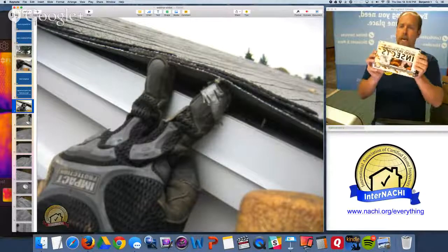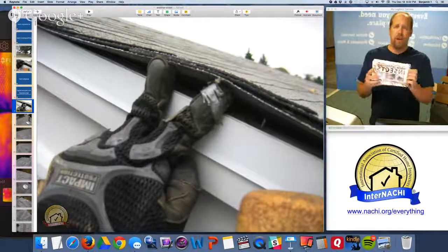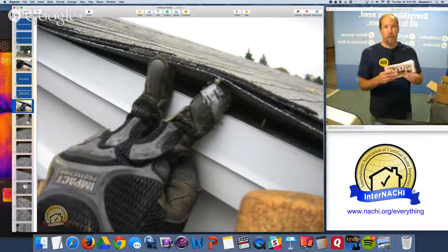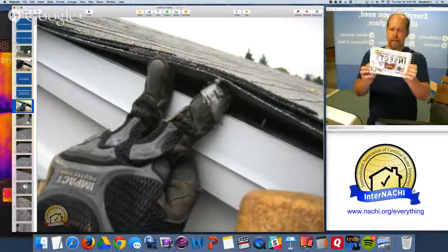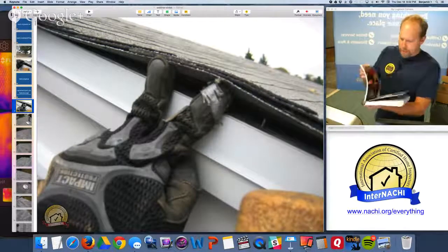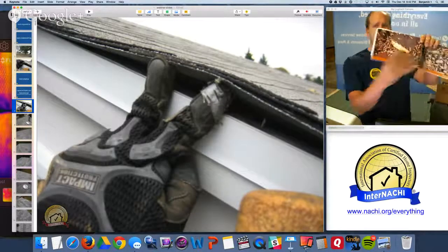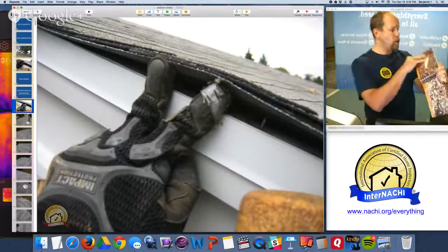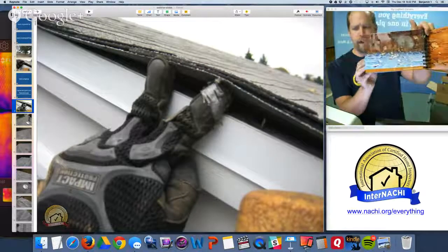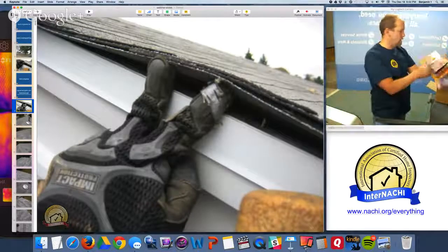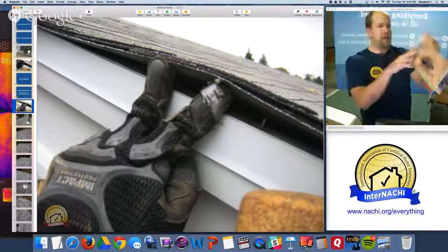You can use one of these. If you're doing a home inspection, you're concerned about anything that destroys wood. Well, moisture destroys wood, moisture and fungus and wood-destroying organisms. Insects also destroy wood. And you can use this field guide. It's laminated, and you can use it to help confirm what you are seeing. So you flip through it, and it helps you identify the insect that you're looking at, or the damage that you're looking at, what kind of beetle it is.